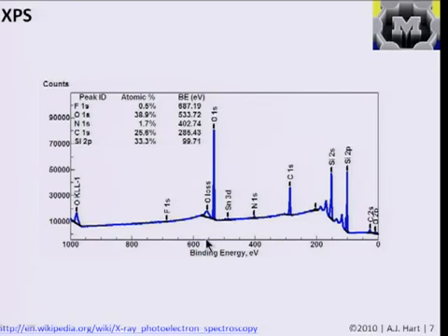And if you know, for example, what the binding energy of an oxygen peak or a carbon peak or a silicon peak would be, you can then get some qualitative and quantitative information on the characteristics of the material. And the important thing here is also that the binding energy for a particular element depends on its bonding configuration. So if you have, say, silicon bonded to one oxygen or silicon bonded to two oxygens, you're going to have peaks in different places.